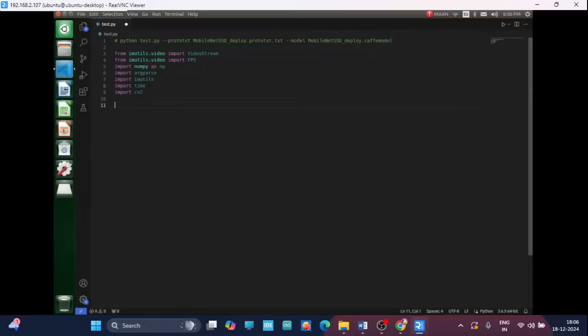Okay. So now let's initialize the GPIO pins. So GPIO.setmode. The m should be small only. Instead I'm going to pass GPIO.BOARD, I'm going to take the board pin numbers only, and then GPIO.setwarnings. Here I'm going to pass False. Okay. So see here, it suppresses the warning when GPIO pins are reused.